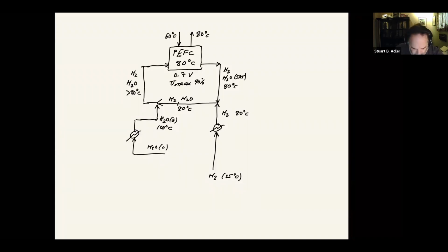Okay, so that kind of outlines the fuel side. We're putting in hydrogen, we're consuming hydrogen, we're recirculating some hydrogen, and we're feeding in water. On the air side, we also are going to come in. So here would be air. On the outlet, we're going to use up some of the oxygen, but the nitrogen will go through.